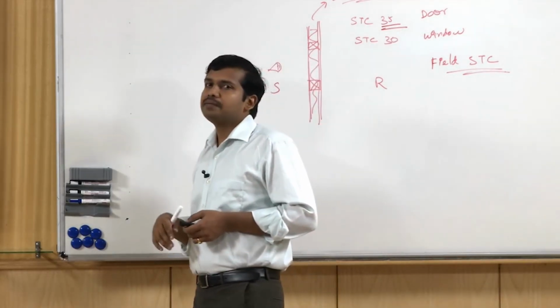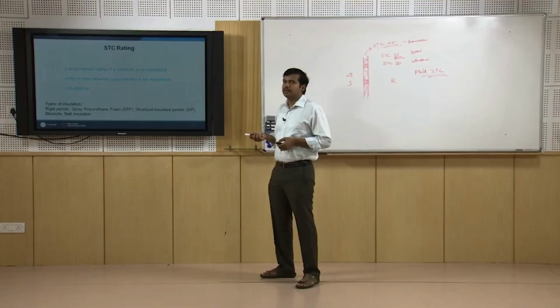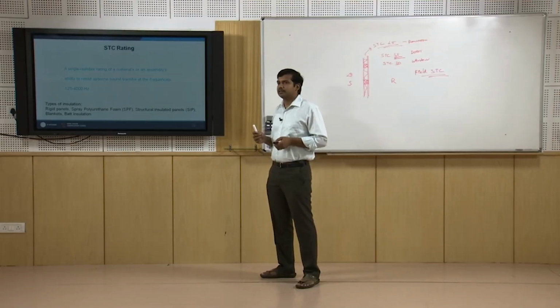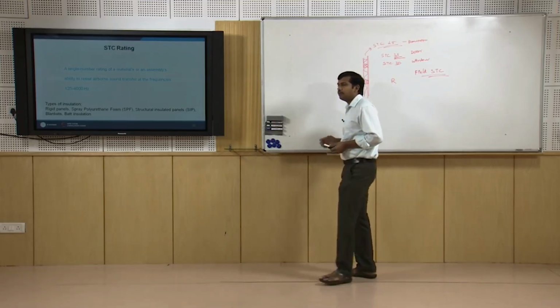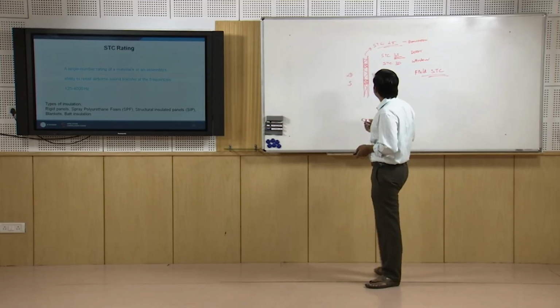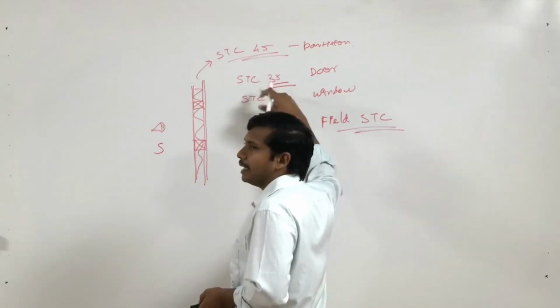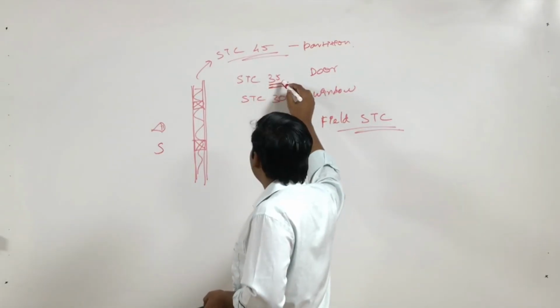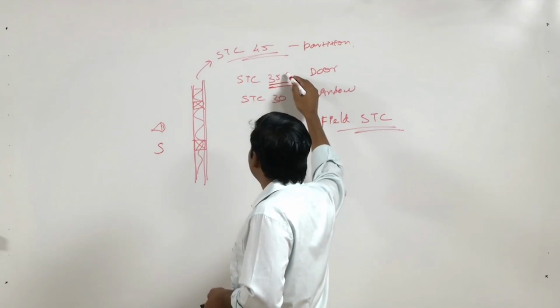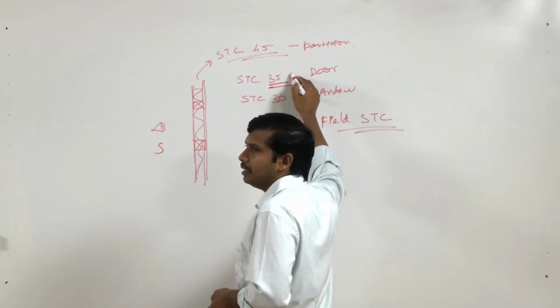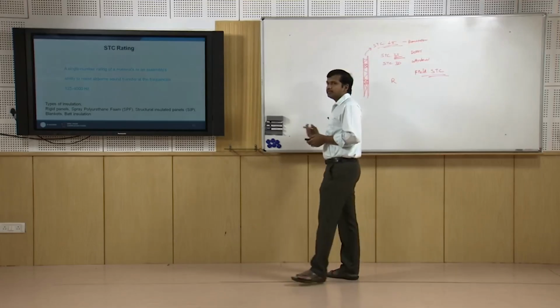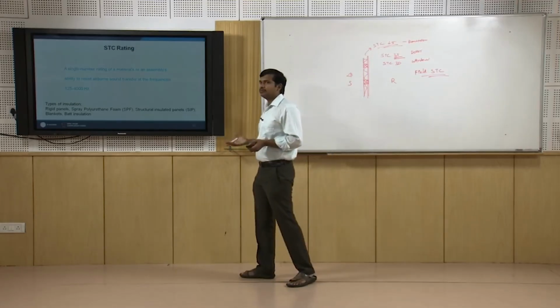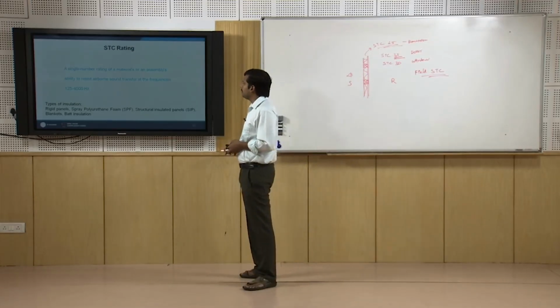Moment you have certain installation related things, you cannot do such a fine installation like they do a testing in the laboratory. So accounting for all that, if you are doing a practical design, go for a slightly higher STC rating. Instead of 35, it is advisable to go for 38 or 40 STC, so that you can actually achieve an STC of 35. It is a general design consideration which any acoustic designer typically does.